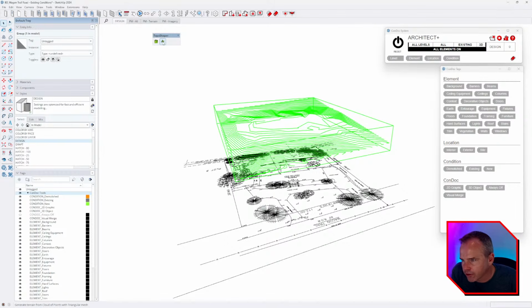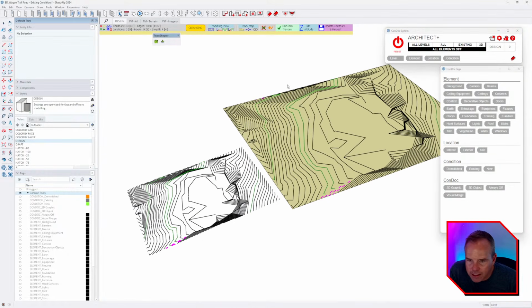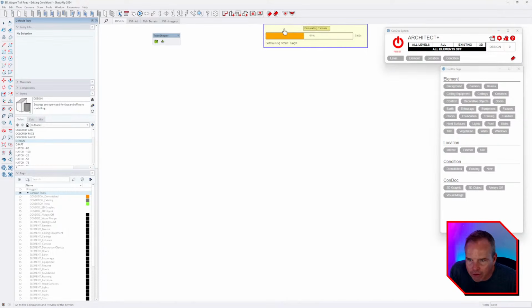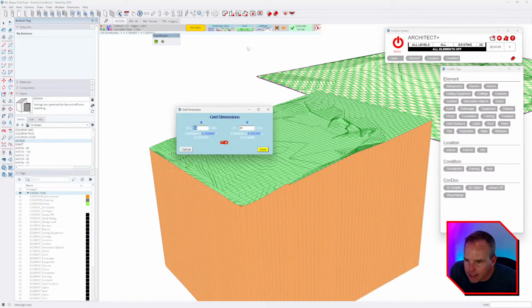So it's my understanding that you first use generate tri-mesh terrain cloud along with the contour lines, and then you move on to generating a quad mesh, which is much easier to work with. Again, you go for a working view like this, and this is one of those tools that I just never really got into all the different options. I think this one's a little bit simpler. We'll just hit calculate terrain, and you could mess with your grid, although when I look at this, I'm fairly satisfied with the grid as it is. I think we're good there.